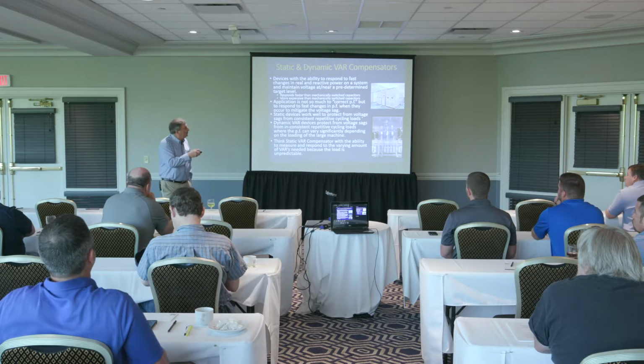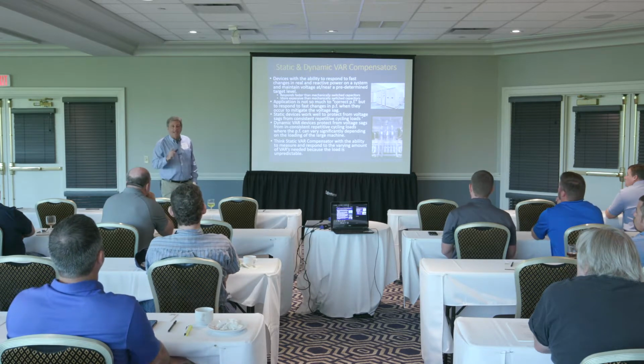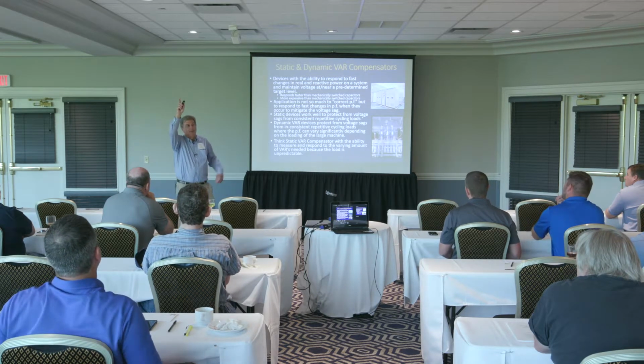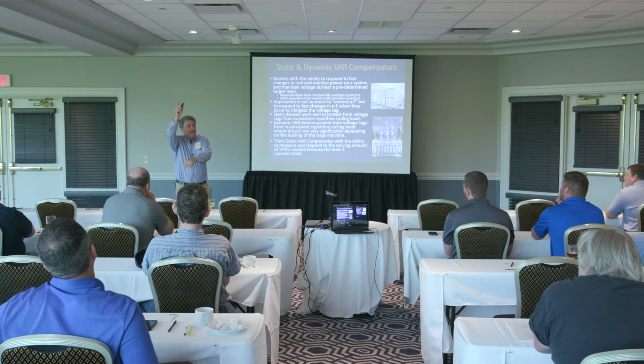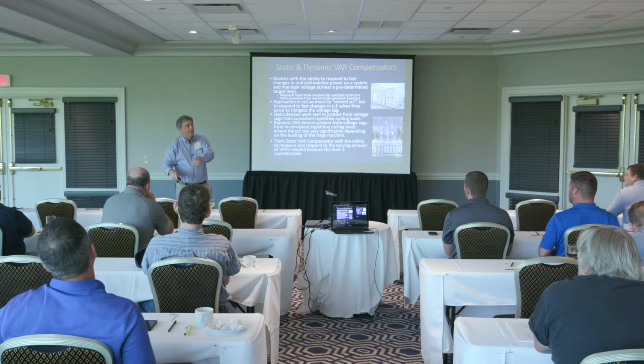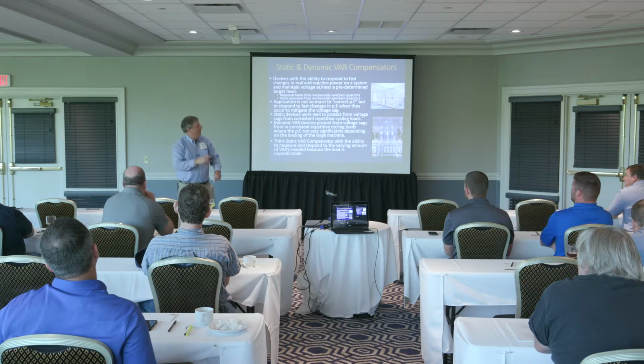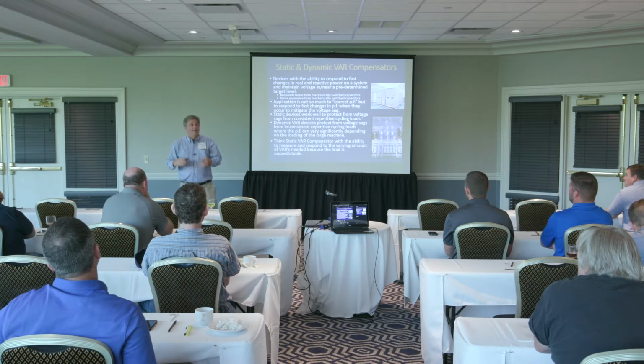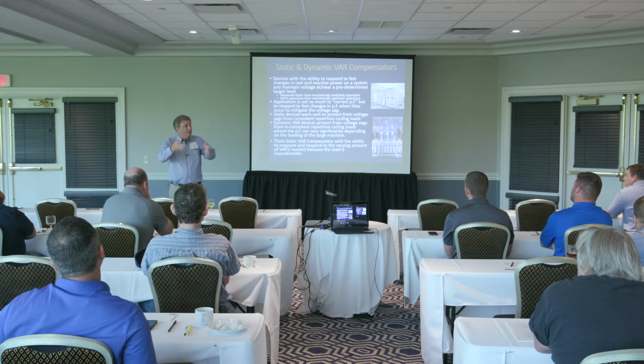So the VAR compensator is fast enough to see that current shoot way up, power factor shoot way down, that causes the voltage drop, and connect the right amount of VARs into the system really fast so that you don't see, a mile down the road at your plant, nearly as big of a voltage drop when they start the car crusher motor.